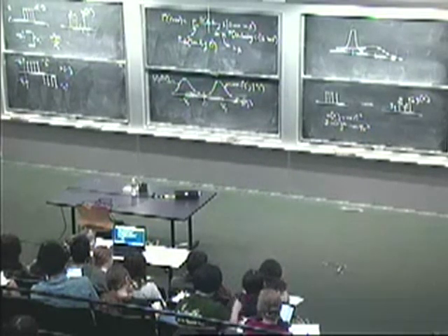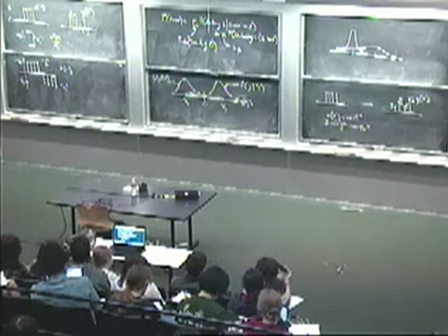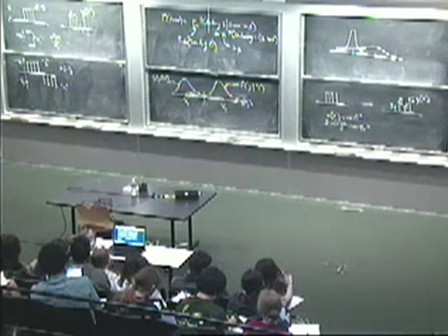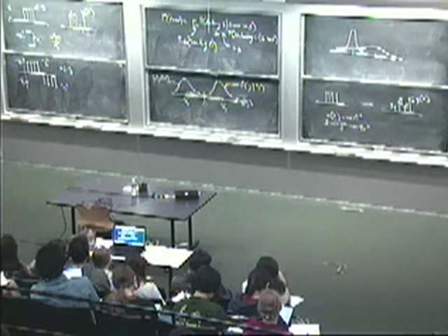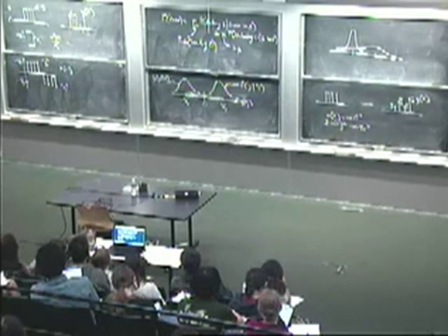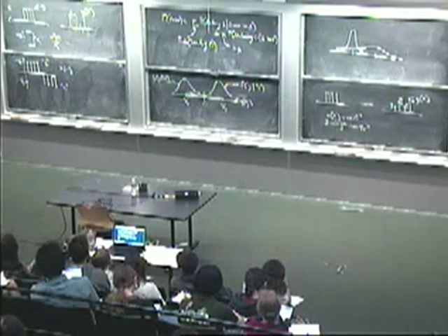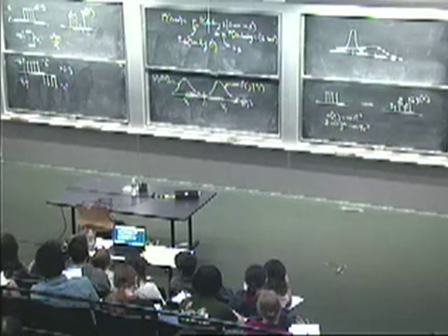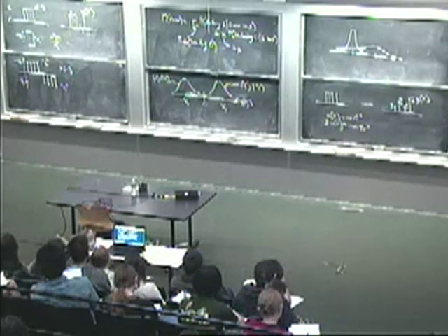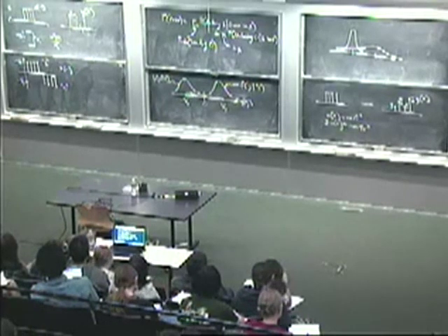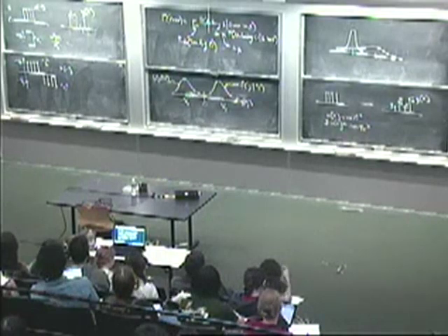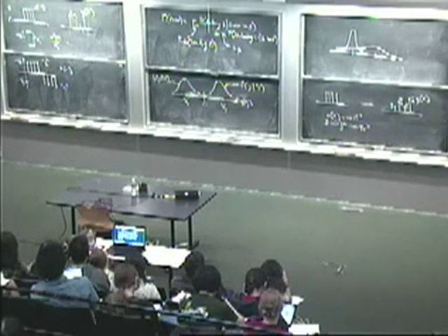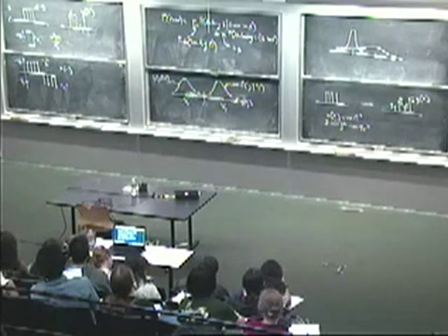Scaling by a particular number scales the variance by the square of that number. So the Gaussian you're adding in here has a variance which is sigma squared times the sum of the a n squareds. That's what the variance of the Gaussian is. See, you can actually write a very simple optimization problem. What choice of weights maximizes the signal-to-noise ratio? And you discover, indeed, exactly that you're going to put the largest weight on the largest sample.